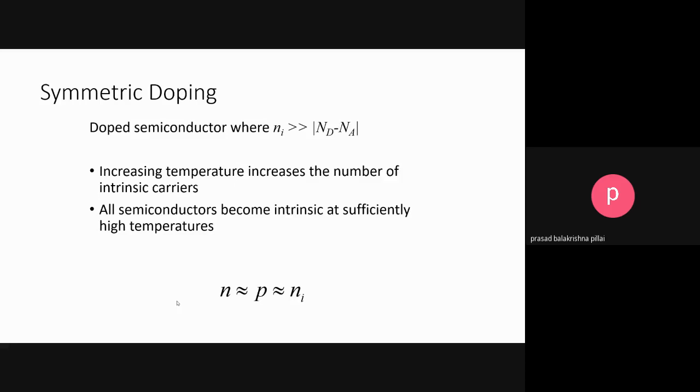One is in the conductivity temperature graph. You have two regions. One is the extrinsic conductivity region. The other one is the intrinsic. So you will be taking your graph to the intrinsic region, and there you do the calculation. That is very important when you do the experimentation. So this is how the conductivity varies with the temperature. That is a very important result.